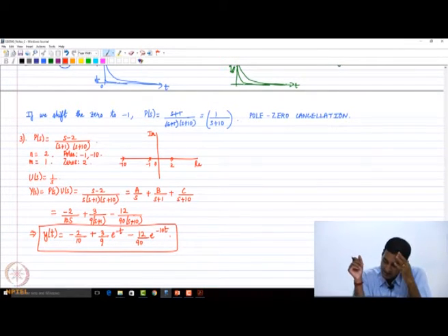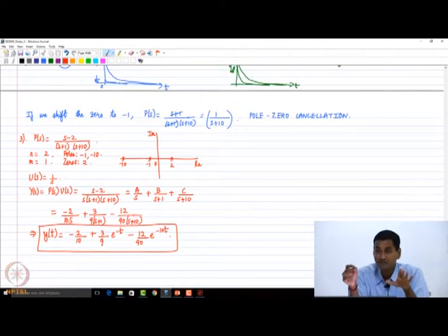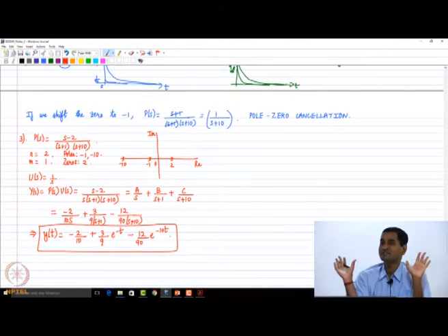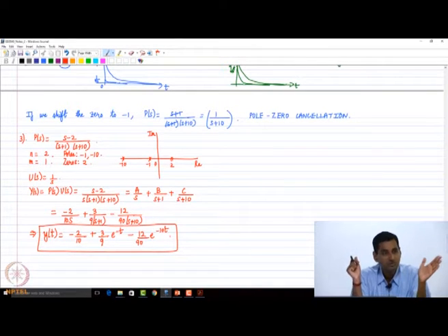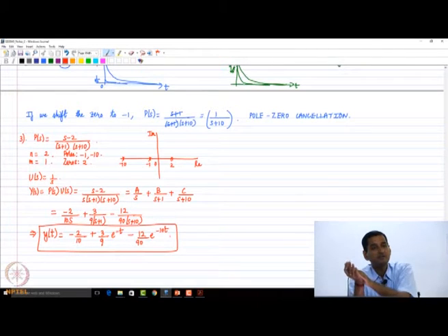So once we have this expression, right? So for y of t, once again you could observe that the system is stable. Poles are in the left half complex plane, and poles are the same, right? I've kept the poles the same in all these problems. Why? Because we want to investigate the effect of zeros. So I'm not even touching the poles, right? So we have shifted the 0 to +2, to the right half plane. So the system is still BIBO stable.